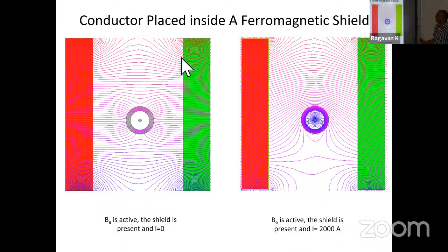Okay. Now, why do we say the conductor is experiencing no force? Let's see it from two methods. Let's first use the easiest method that we know, which is BIL. If I want to use BIL, I need to know the external field's value at that point, and then B into I into L. So based on this figure, I have a current I here, and in this method, I don't care about the field coming out of the conductor. I only need the information of the external field. So B into I into L here is 0.